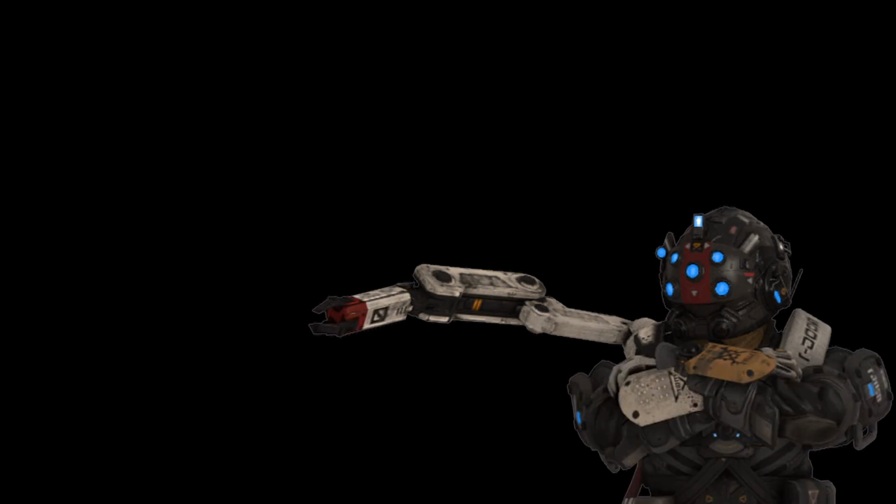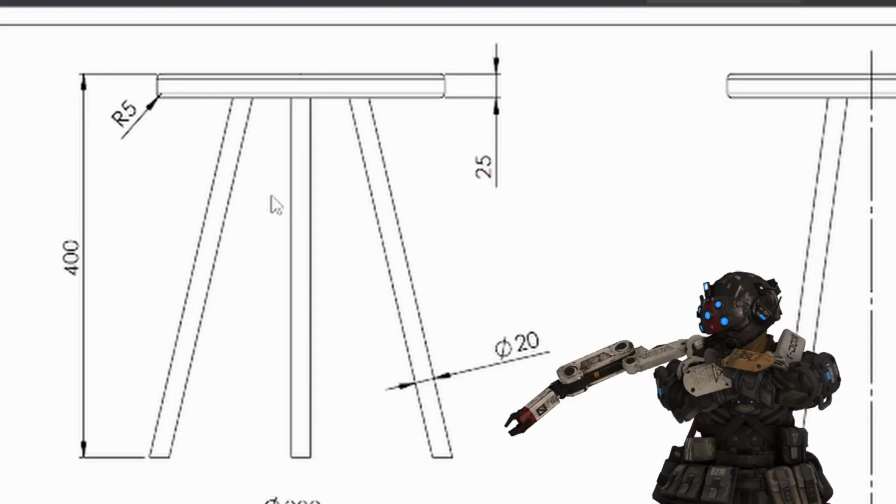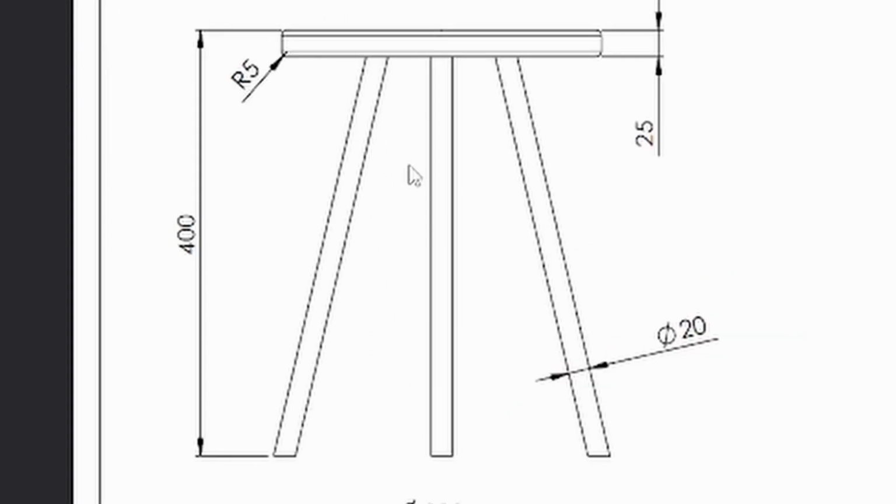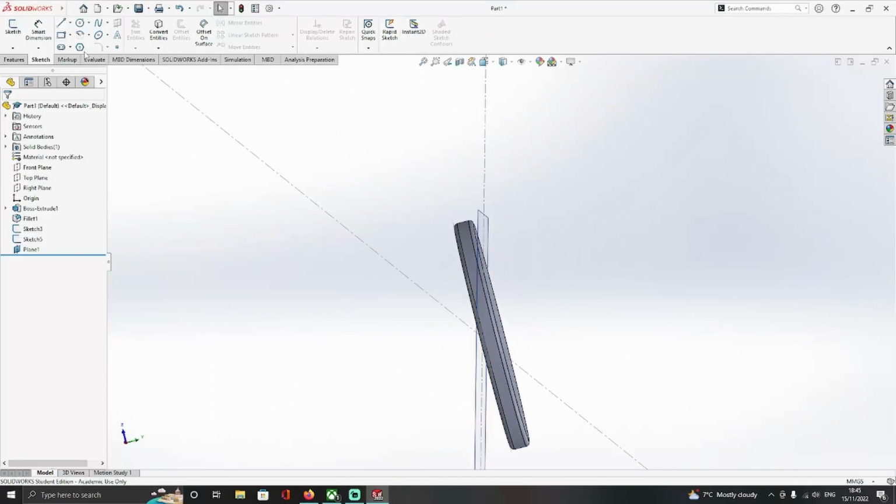No, what I mean is that to make the legs, we need to consider one final piece of information. If you look here, the blueprint shows that the legs are flat at the bottom. Look closer. The bottom face that would be in contact with the ground is parallel to said ground. That would make sense, so we need to make another plane that will define the alignment of the bottom face. Oh, I forgot to mention, the blueprints do not give us the length of the leg, only the distance from the top of the seat to the ground. So we'll need that plane for that too. Let's get that plane.